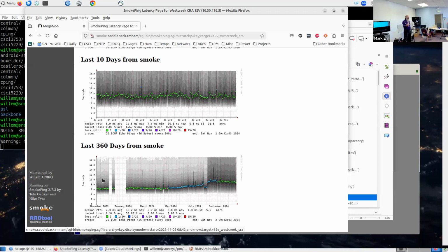You'll see that they come with all kinds of nice things to actually configure them. So right now, you'll see there's a lot of green lights being shown here. That's because this radio is talking to that radio. So obviously not much of a challenge there. But this is very convenient for actually peaking the link. You can just use the lights there to do approximate peaking, both in element and elevation. And then you can actually switch to the software and fine tune it to actually get the best overall link. The nice thing about something like this is that it's IP in and IP out.